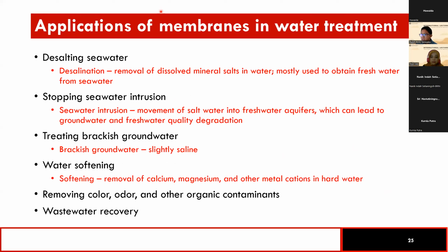Okay, so these are the applications of membranes in general water treatment, aside from wastewater recovery. Okay, first, desalination, or the removal of dissolved mineral salts in water. And this is mostly used to obtain fresh water from seawater. So this is usually done by nanofiltration and reverse osmosis.